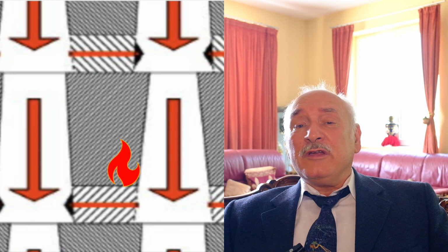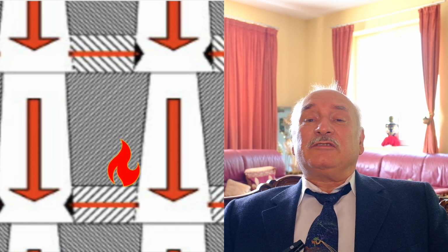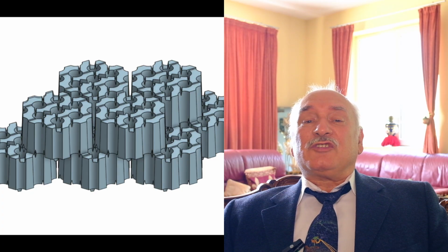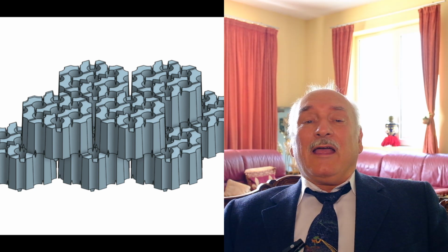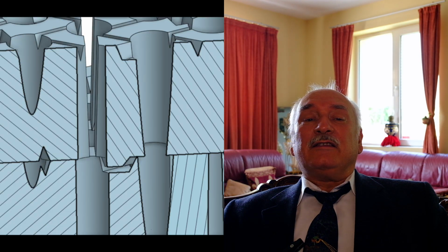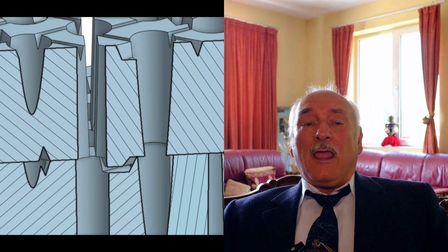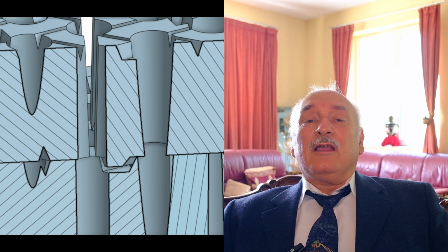The larger the voids, the larger the heat transfer surface, and therefore the more heat enters, and the faster it is transferred to the blast furnace at the higher temperature at the required flow rate. The problem is that large holes mean small refractory mass. If the mass is small, there is no possibility to transfer enough heat.